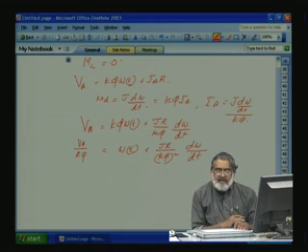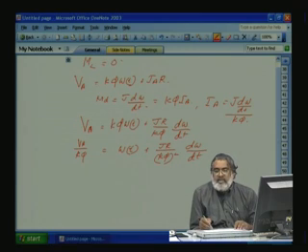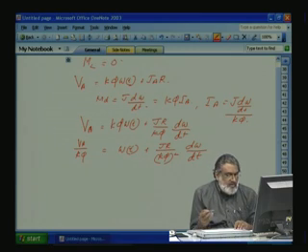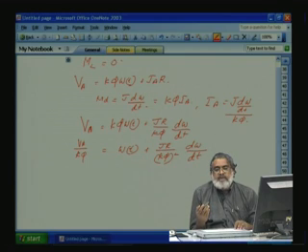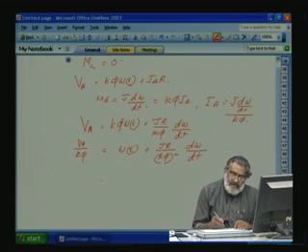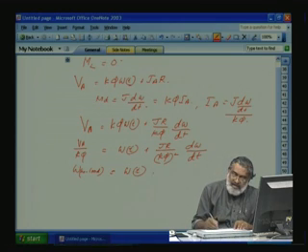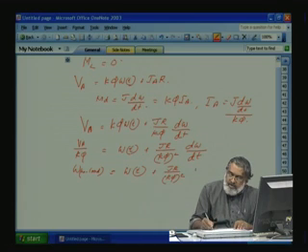What is Va by K phi square? When d omega by dt will be 0, when the machine has reached the no load speed, full speed. Then omega t, that no load speed Va by K phi, that we have derived in the last class. So Va by K phi is equal to omega no load, that for applied voltage what is the maximum speed it can go. Omega no load is equal to omega t plus J Ra by K phi square into d omega